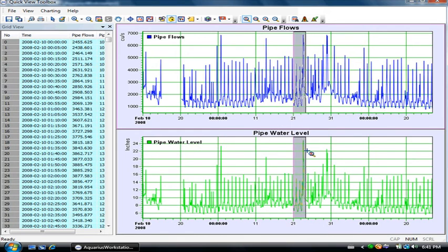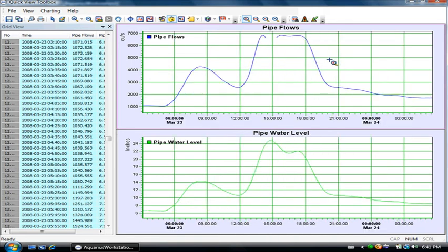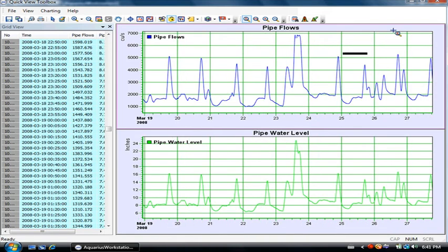In this particular case right here, if we zoom in on it, we're going to see that there was one specific time where we went over 24 inches, and we've actually got a gap value now for our flow in that particular case. So those two are going to line up because this is actually where we want to go in and use a separate calculation and then splice these two time series together. So we're just going to zoom out on that.